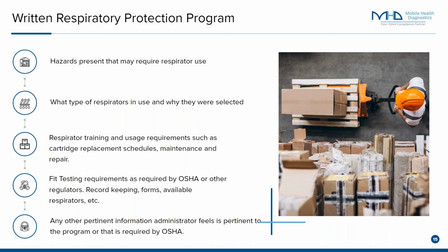A lot of organic vapor cartridges have about a 3-month, maybe 6-month time that they can be used. Once the employee tears open the package and puts that cartridge onto their respirator, the clock starts ticking. That's typically because a chemical reaction is involved, or it's using a charcoal or carbon filter, which has a very specific timeline. So referring to the manufacturer specifications for each cartridge is important, and that should be part of the written protection program as well.